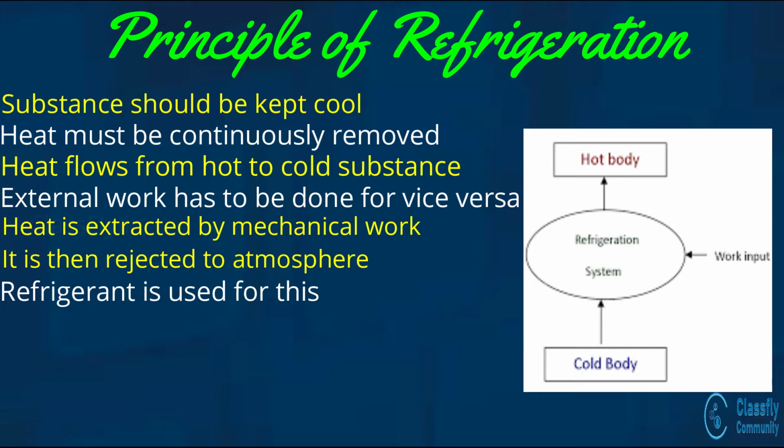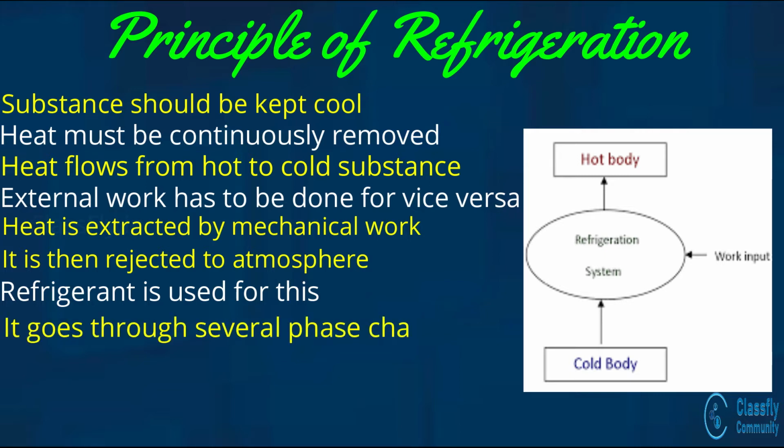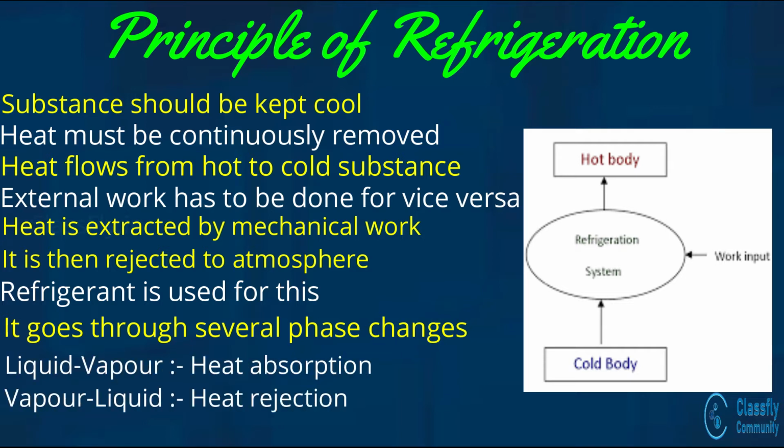Well, here the refrigerant in liquid state is made to circulate in a cycle and goes through several phase changes. During its change from liquid to vapor, it absorbs heat from the substance and during its change from vapor to liquid, it rejects the heat to the surroundings. This cycle is repeated again and again in order to maintain this low temperature which is required to keep the substance cool.